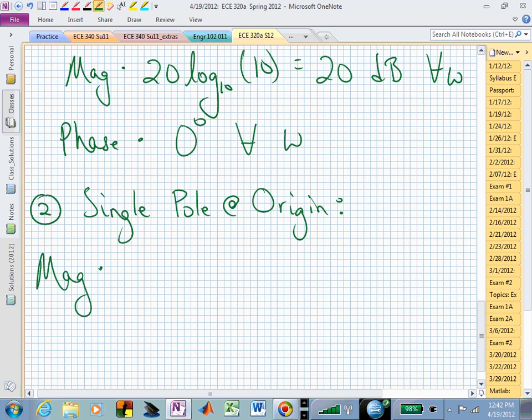It never stops. It's always on. If I have a pole at the origin, it's going to be really, really big at low frequencies and really, really small at high frequencies. And that line, if I just have one pole at the origin, the slope we know is 20 dB per decade down, or minus 20 dB per decade. And it's always sloping. There's no break or kink in that term. Likewise, if I had a single zero at the origin, it would be in the other direction as far as its slope. It would be really small at low frequencies and really high at large frequencies.